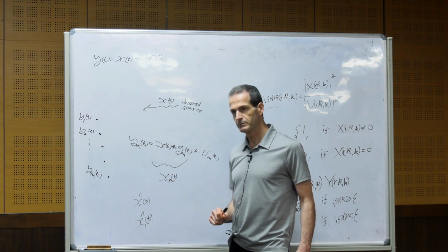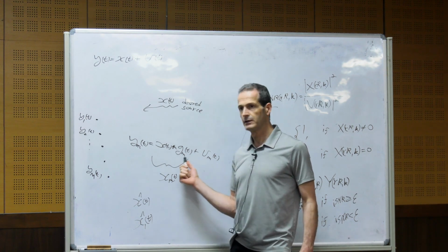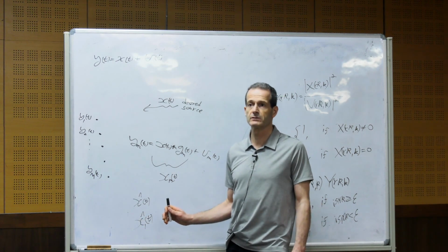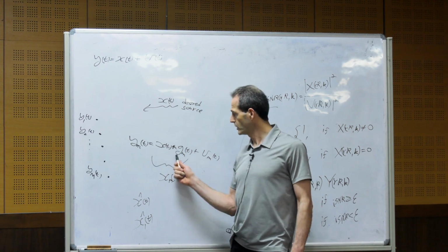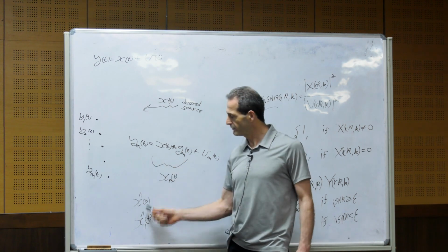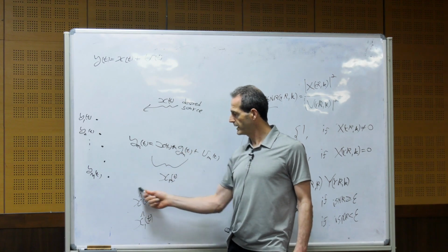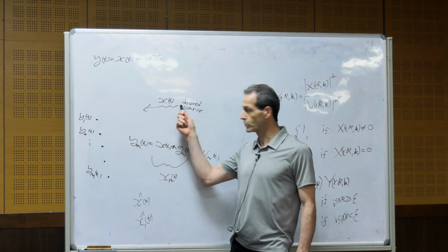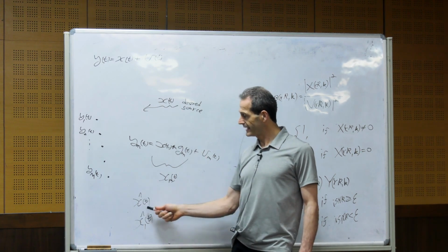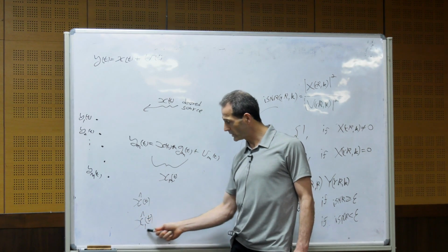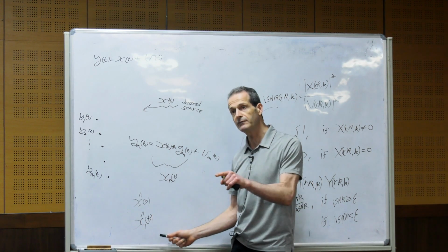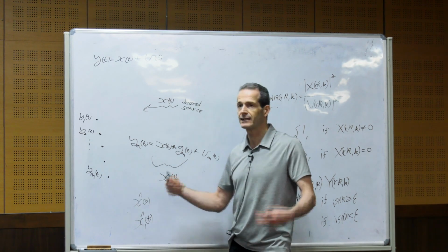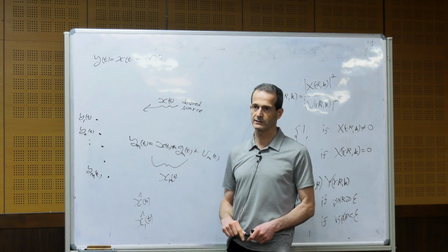Inverse transform, what do you mean? The impulse response? Here, I don't need it. I don't know the impulse response. I don't know G1t. If I knew that, maybe I could estimate the source. But I don't estimate the source signal. I estimate the source signal as it is received in one of the sensors. And the sensor that I choose, I call it the reference sensor.